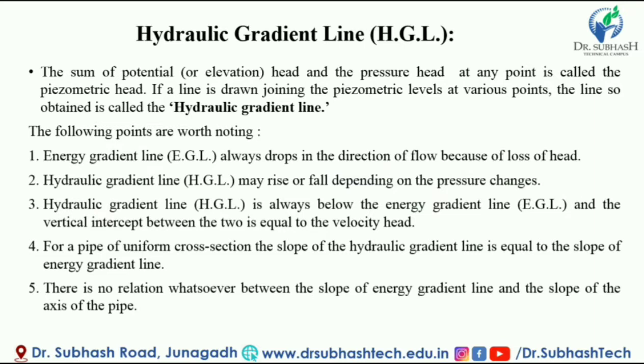Okay, the second one is that the hydraulic gradient line may rise or fall depending on the pressure changes. If the pressure changes, the hydraulic gradient line rises or falls accordingly. It does not always fall. It follows the pressure energy. If the pressure is high at some point, then the hydraulic gradient line also rises.